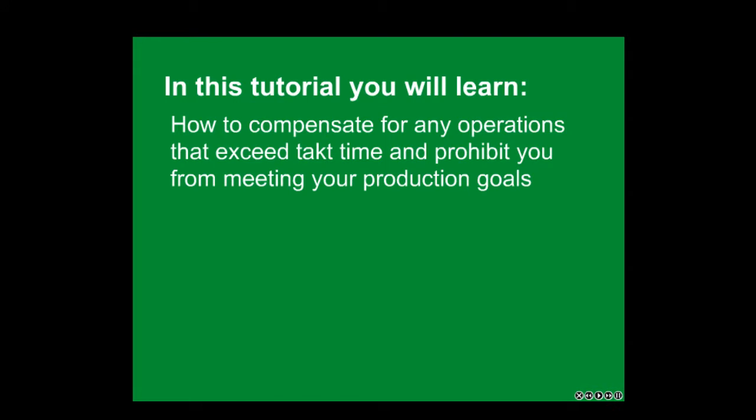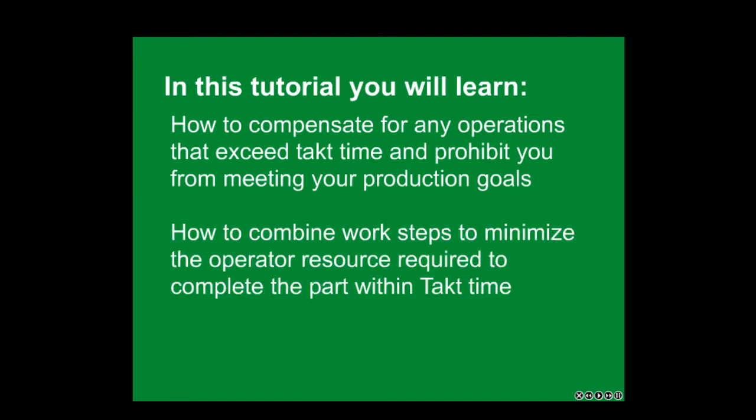In this tutorial, you will learn how to compensate for any operations that exceed takt time and prohibit you from meeting your production goals. You will also learn how to combine work steps to minimize the operator resource required to complete the part within takt time.